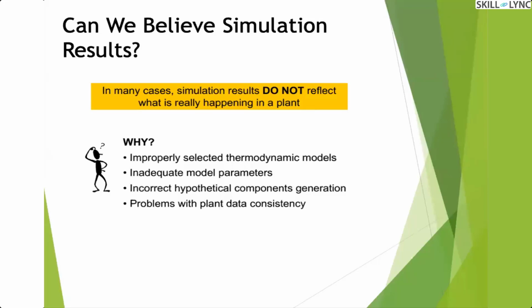If you choose the wrong thermodynamic package, it will not predict the azeotropic formation. Even in that case, if you select a wrong thermodynamic package and plot the XY plot, you will not see any azeotropic formation. But in reality, there will be azeotropic formation, and again you will end up with wrong results. So in all of this, you should take care when you select the simulation property package.